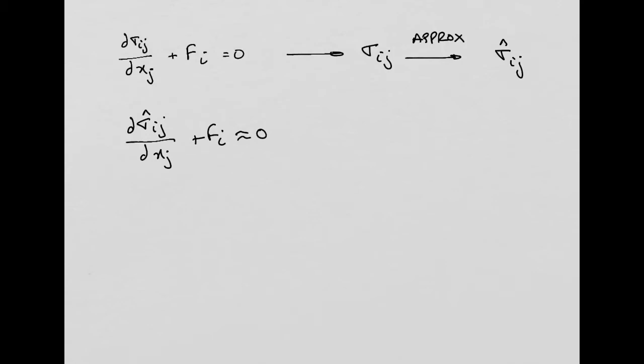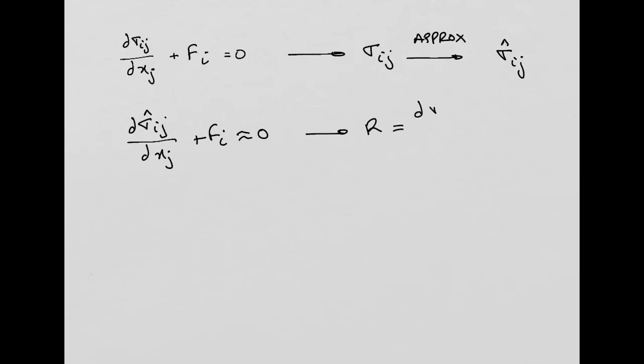My residual is going to be equal to the derivative of my approximated stress field plus Fi, okay?